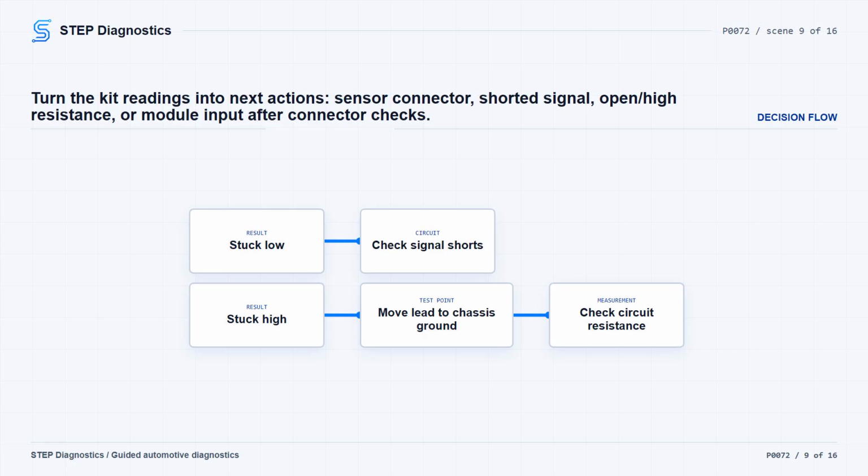If the circuits do not show excessive resistance, inspect all related harness connectors for pushed out, spread, corroded, or dirty terminals before condemning the ECU. If no issues are found, the ECU replacement decision is supported by this test path.